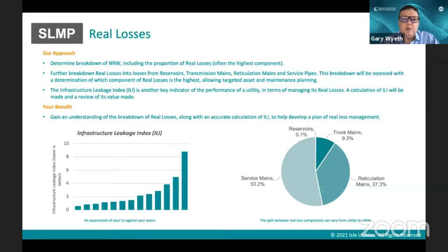They also had an issue with the ferrules where they were buying cheap ferrules to connect the PE into, and they found that cheap is not always best, as we know. So they've had to change the ferrules that they used for a better quality one, which will ensure a better and stronger fit to the PE 100 mains.